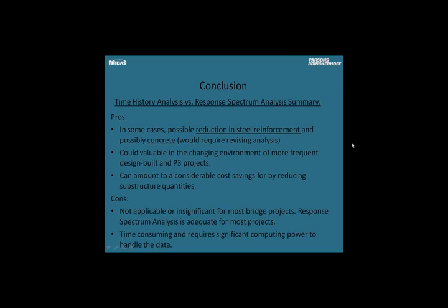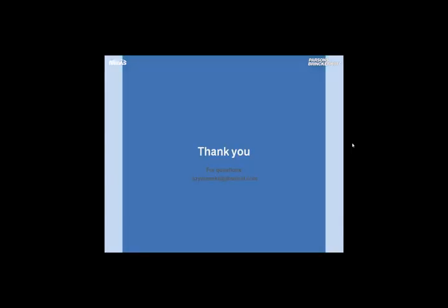However, the cons: not always applicable or maybe even insignificant for most bridge projects. For most ordinary bridges, response spectrum analysis is completely adequate. And also, as I said, it's very time consuming and requires significant computing power to handle the data. I have a brand new computer, and even to run one bent, in some cases my computer crashed. So you really need to have a powerful machine to perform a fully robust time history analysis.